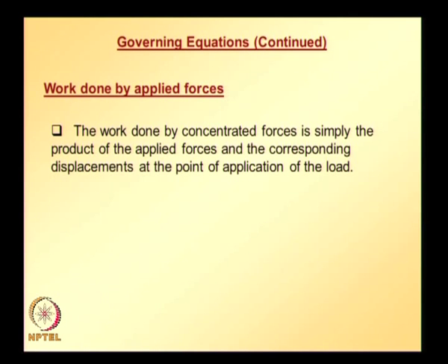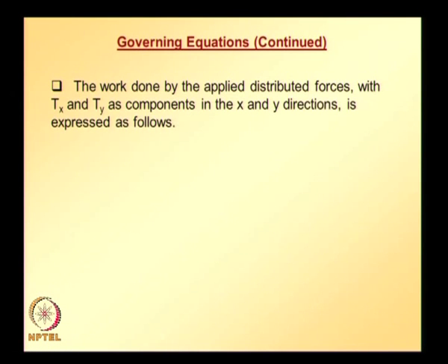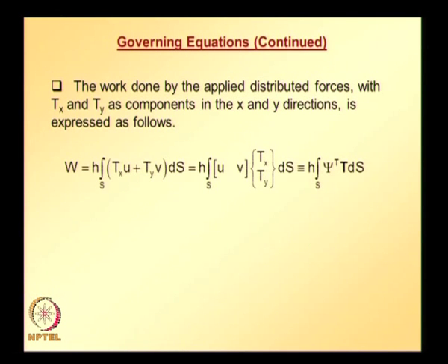And if it is a distributed load, the work done by the distributed load is given by traction components in x and y directions multiplied by displacement components in x and y directions, integrated over the entire surface over which tractions are specified.